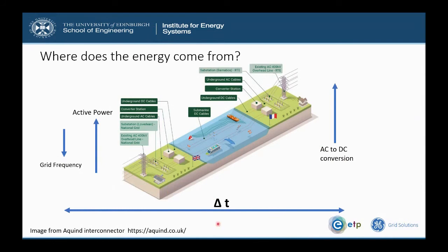As I said before, an MMC does contain some capacitors. So in theory, it has a little bit of stored energy. Each of these cables has a capacitance, so again, there should be a tiny bit of stored energy there as well. What I've been looking at is what the physical limits are in a situation like this, if we start to drain the capacitors on the English side until the French side can ramp up the export across the DC link.